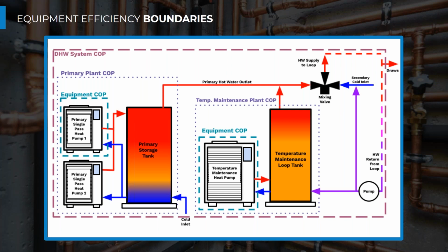Yeah, that's a great question. So we did add equipment to get that third-party control system. There's some kind of brain or third-party controller, right? But we did also specify more temperature sensors than we needed to control the heating cycle of the heat pump, because we wanted to look at the outlet water temperature here, the outlet water temperature here. We could get the water temperatures from the Colmac heat pumps through their control system, but also look at this and then look at those electrical elements and whether they're on or off that are providing backup to the system.